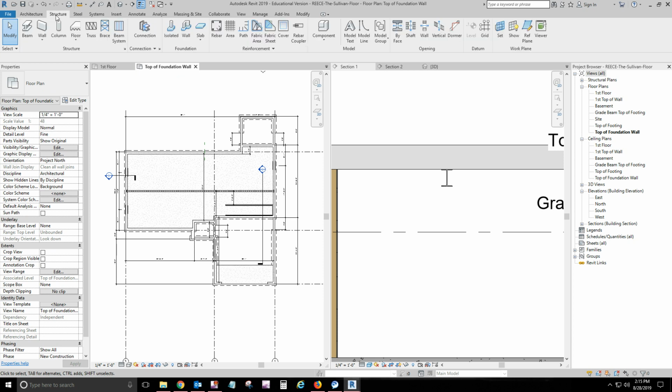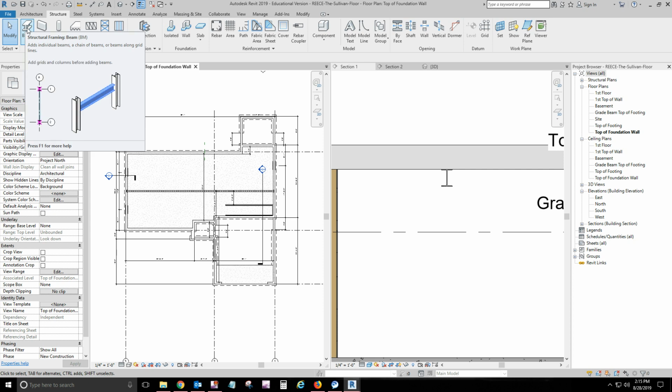With this one, instead of doing a sweep, I mean, I could do a sweep or an extrusion just like we did before. In doing that sill plate around the building, it's easier and quicker to do a sweep than individual pieces of wood. That's why I did that. Unless you're using Revit to do quantity takeoff on a list of materials, it works just fine. Okay, it models what you want.